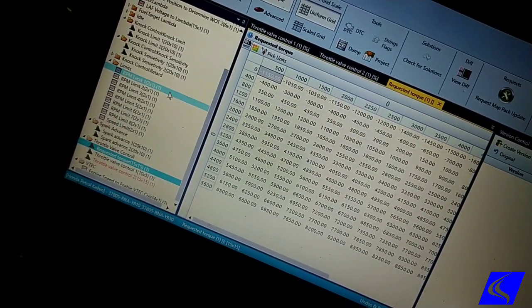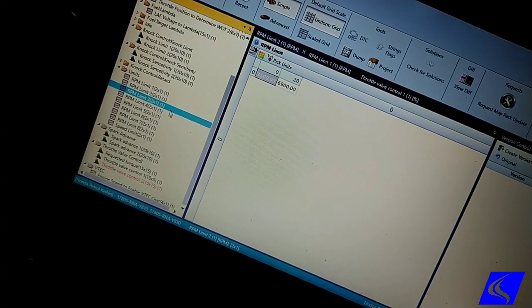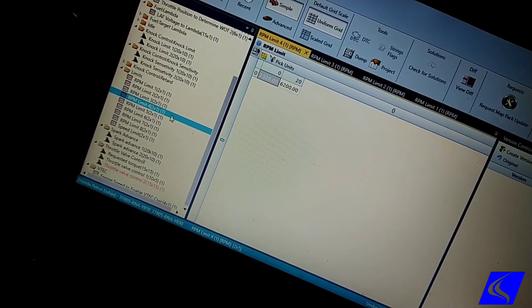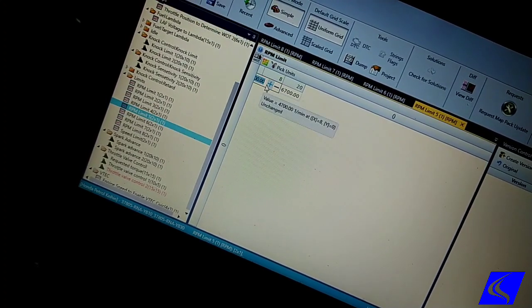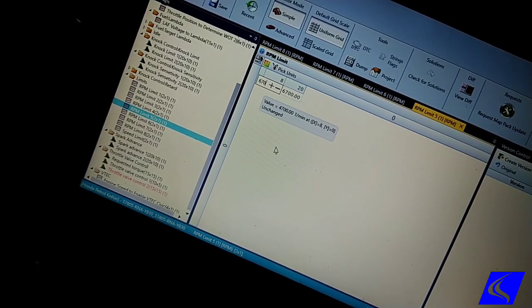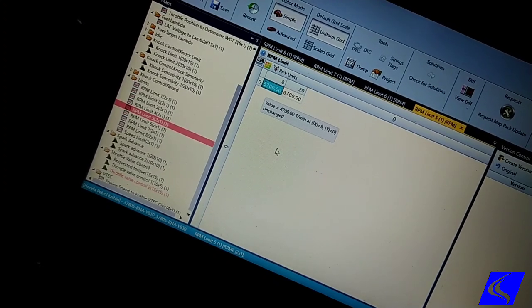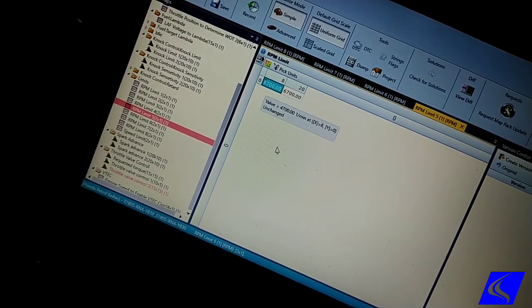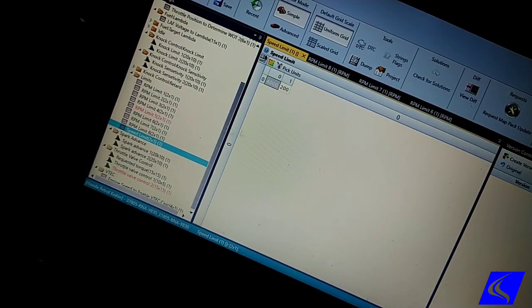So then this one, we're looking for the RPM limit at idle and park and neutral. This setting basically tells us that when the car is at park or neutral, it can only rev until 4,700. So we're changing that now. So even if it's at park and neutral, we can now rev to redline. And of course, everybody likes speed limit.